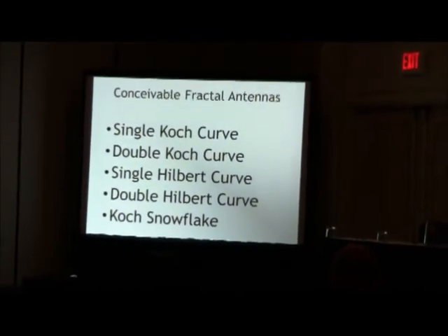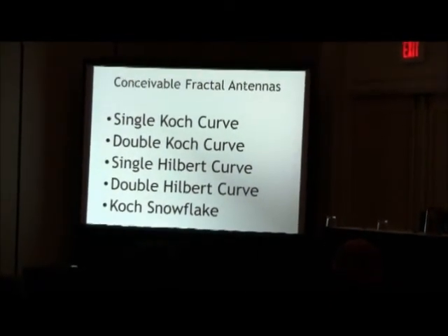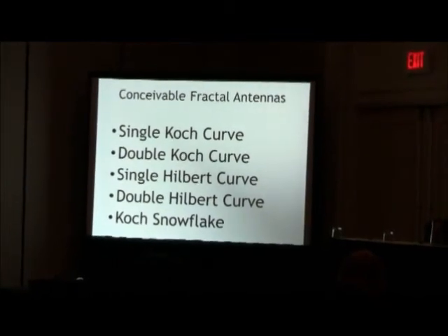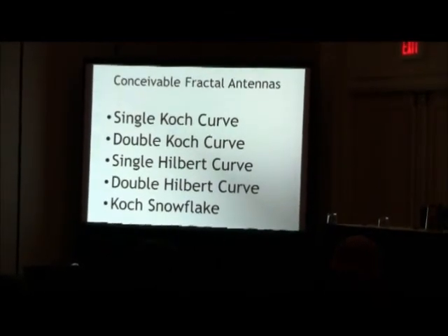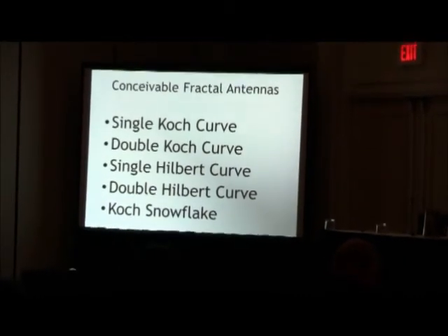And by using the 4nec2 simulator and optimizer program, it became incredibly easy to perform spectrum sweeps, twirl an antenna 3-dimensionally, observe the 3D radiation pattern, and invoke matching networks.